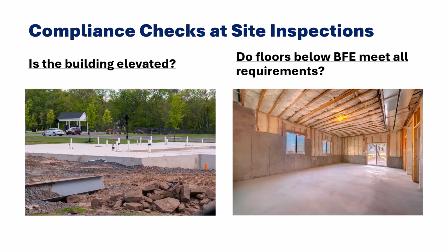Other things you'll want to check in addition to if the building is properly elevated, especially if there are enclosure floors and they are going to be below the base flood elevation: do they meet all the appropriate requirements? Are they not a basement? Are there sufficient openings planned for the flood openings? Things like that.